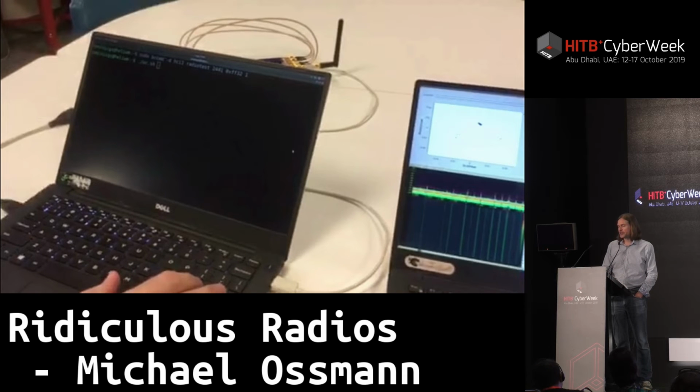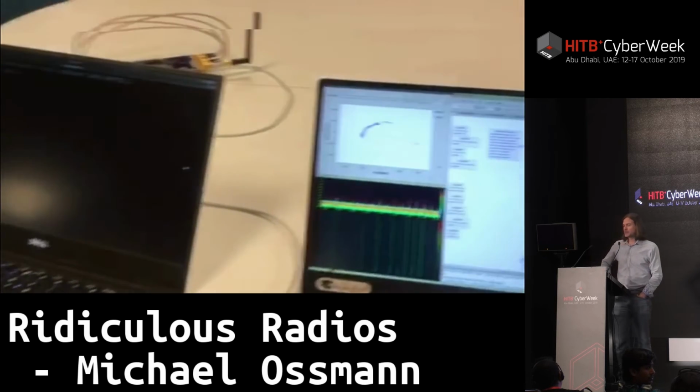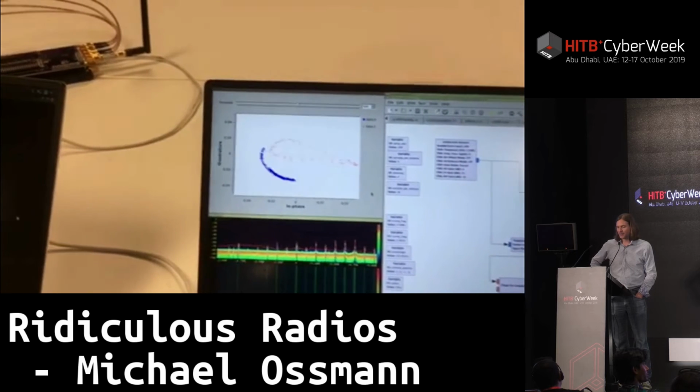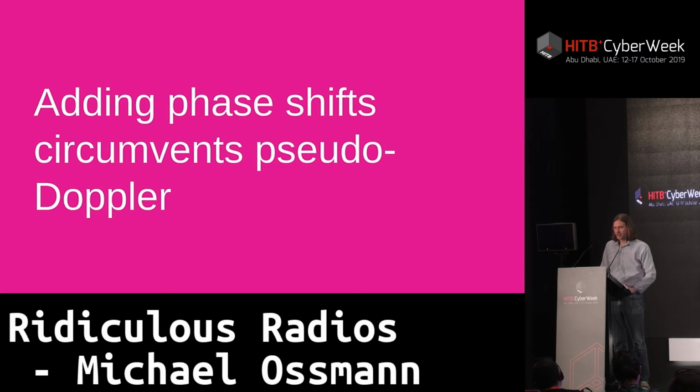And then he's going to turn on his script that starts randomly modulating his phase by switching back and forth between 2 different delay lines. And look what happens to my direction finding setup. Turns out this worked really well. He was able to fool my direction finding setup. I was getting useless information about what direction his signal was coming from.